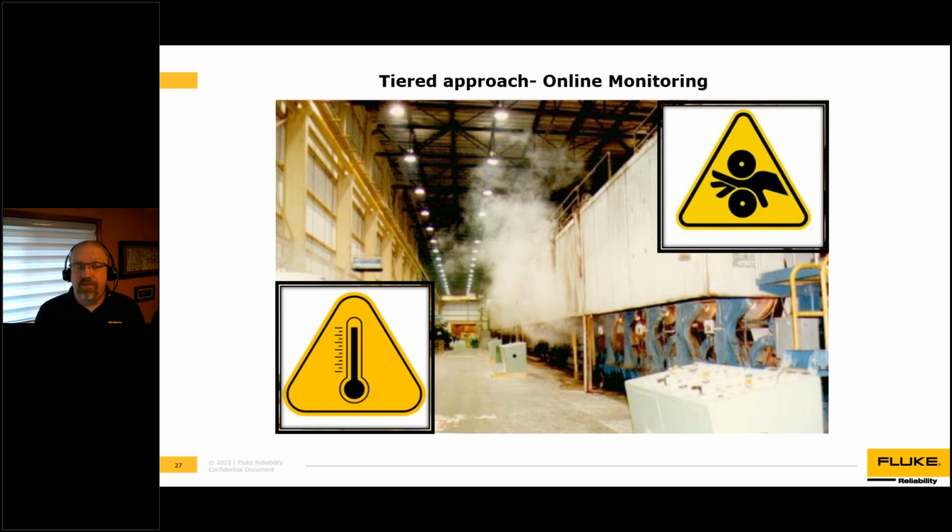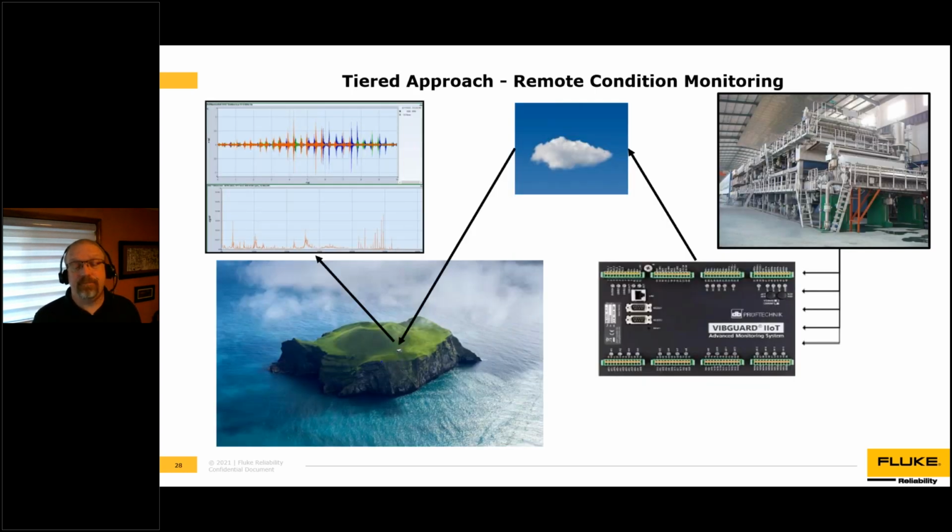Online condition monitoring systems can utilize virtual servers, and this allows the data to be viewed remotely, which in turn allows for remote condition monitoring. Remote condition monitoring services allow off-site personnel to review vibration data. Due to the nuanced nature of vibration analysis, it's helpful for analysts to have a familiarity with your process. So, remote condition monitoring teams review the data and make recommendations to site personnel who then inspect the equipment. It may seem a little complicated, but in truth, it empowers your site personnel to concentrate on the equipment that has progressed into a failure state. And it reduces the amount of time your vibration analysts spend reviewing data on fault-free machines.